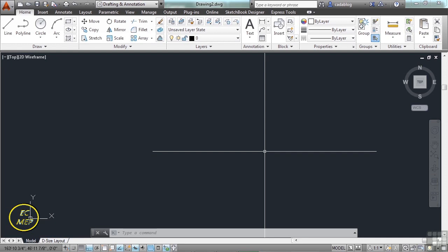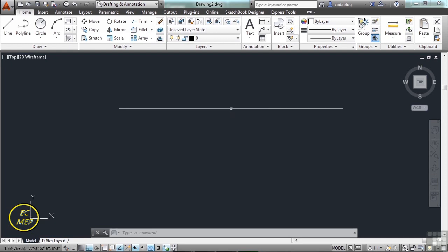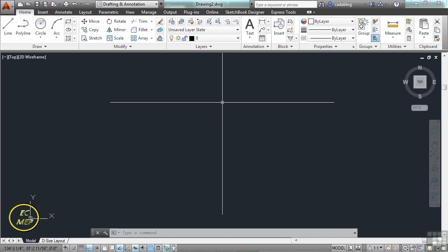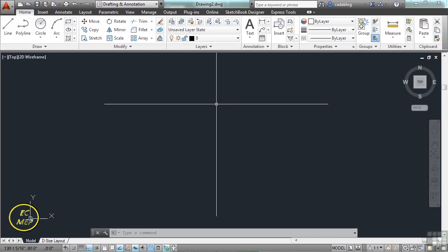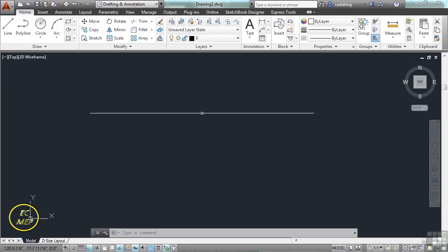In fact, we've drawn many polylines already using the rectangle command. I like to use the rectangle command as a great example because it's very quick to do. 2 points, and you have a nice shape that's easily defined, seen, and worked with. But drawing a polyline can be accomplished using the exact same methods that you draw a line with. So the previous section here in this chapter will be applied directly to a p-line exactly in the same way. After all, a polyline is just a set of lines that are connected together.